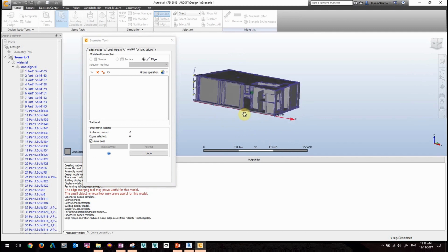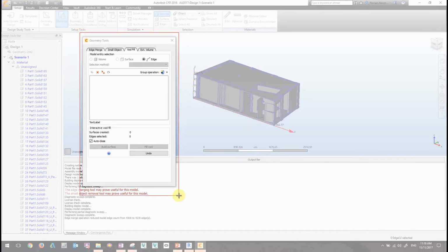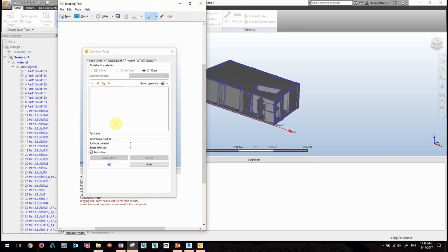This is especially interesting when we, for instance, have a pump and bring this pump in, or I have a valve or anything else similar which we open up, and it comes with a hole. So basically what I can do is select my border and close it up. Because what CFD requires is a volume, because on a volume I can assign my boundary conditions, be it a volume flow, a pressure, or some temperature. So where nothing is, nothing can be calculated.